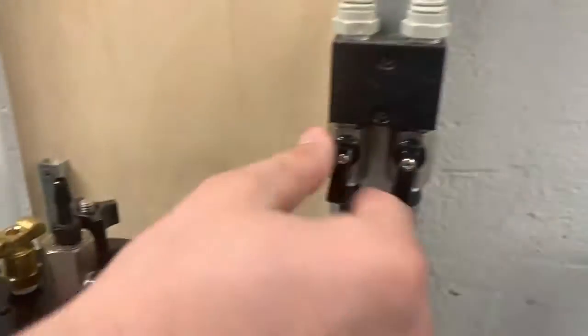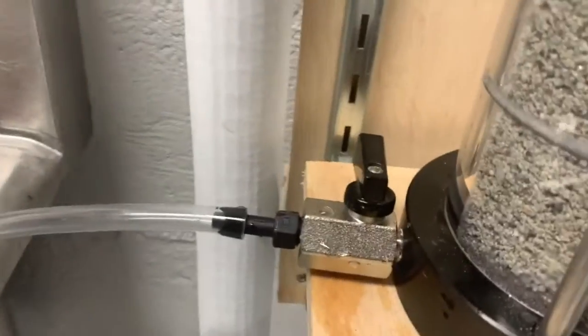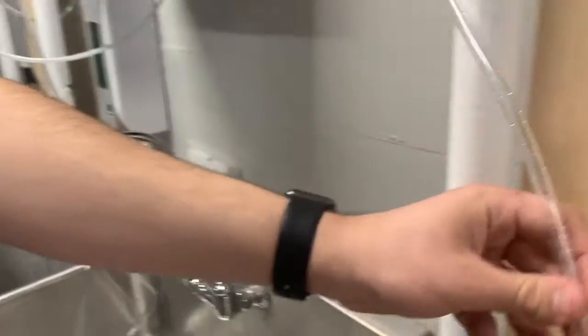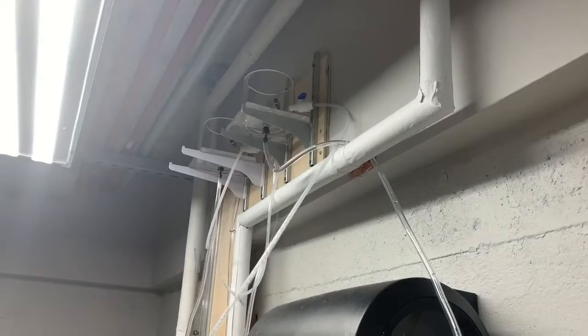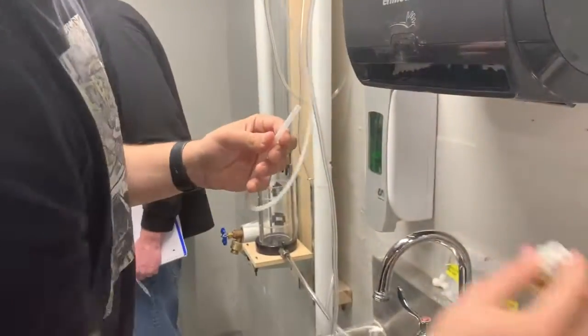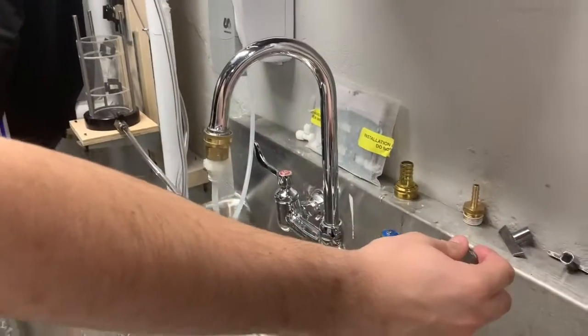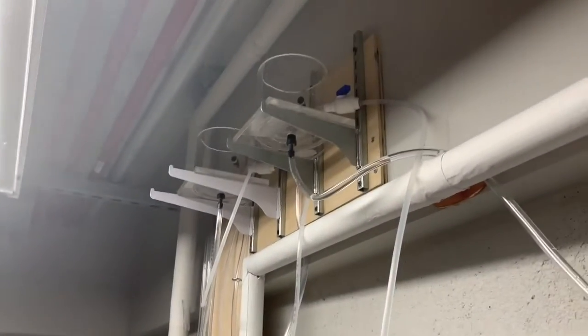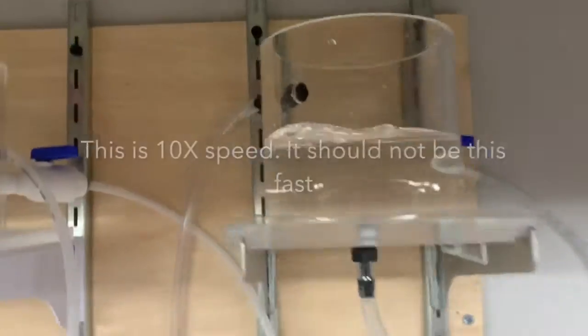Make sure each of the valves on the apparatus are closed. Closed is perpendicular to the flow. Connect the tube from the head tank to the top of the apparatus. Connect the inlet of the head tank to the head of the sink. Turn the sink on. You don't need to turn it that much to get a good flow. Do not let the head tank overfill.